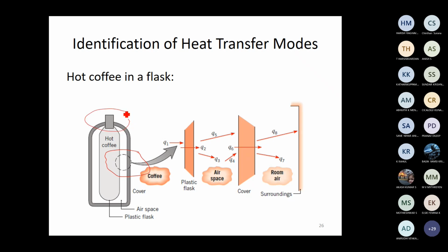This is a small region, and the amount of area of contact is very negligible. We know that heat transfer is area dependent. So higher the area, higher will be the heat transfer. The area is low here, therefore the amount of heat transfer here will also be low. So we will ignore that. We consider only this part. Now this cross section is shown here, enlarged, magnified.